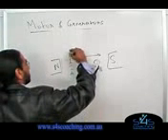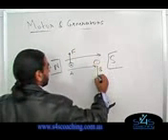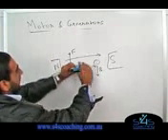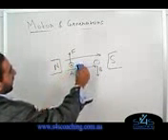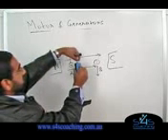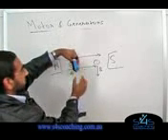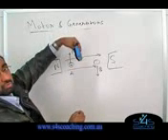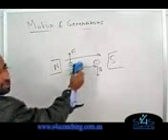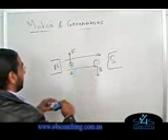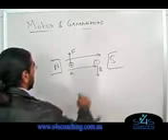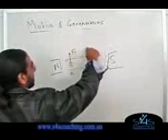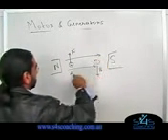So this side gets pushed up, and this side will actually get pushed down. So essentially, this loop will turn. From here, it will turn all the way to there. When it gets to there, the force is pulling one side up and the other side down. Because they're in opposite directions, there actually will be no force. But this will still keep on moving because of inertia. Eventually what will happen, however, is the loop will turn so that A comes where B is and B comes where A is.